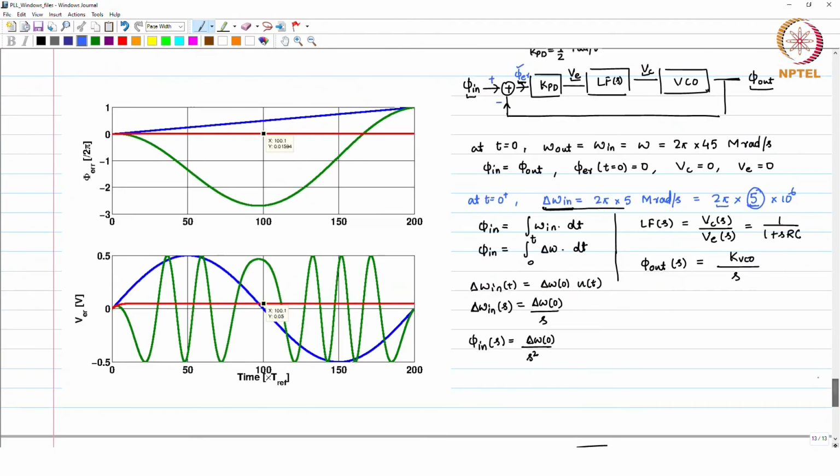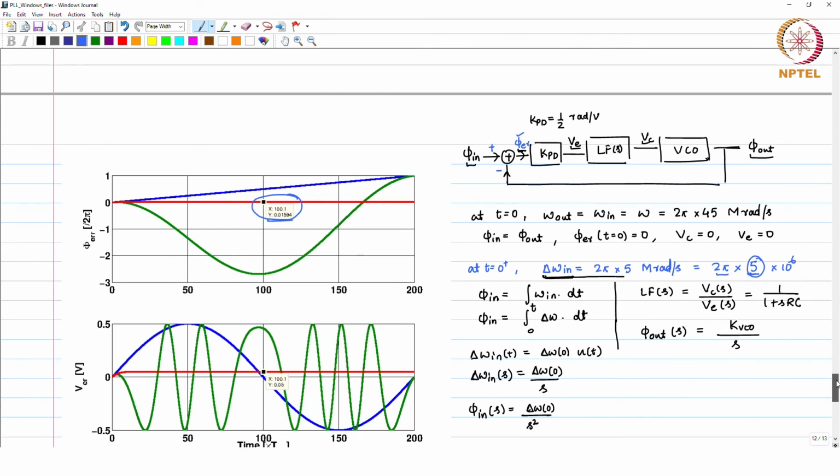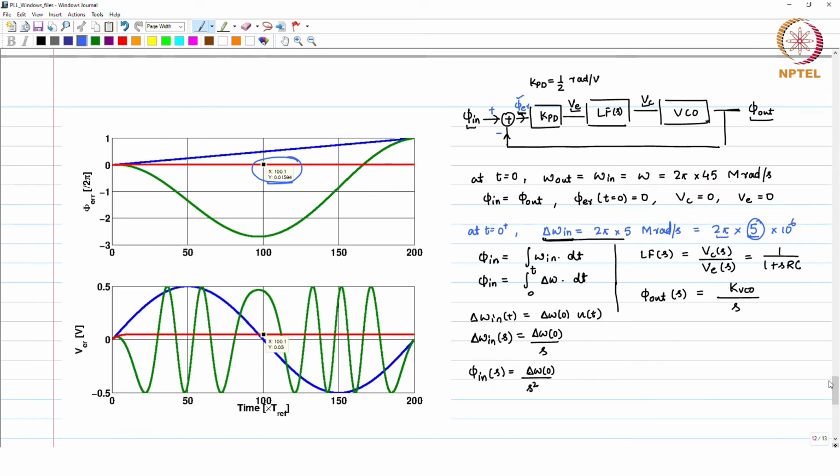Now, we did all this maths, and now if I say that this is the value after doing a small signal analysis, I go and simulate my PLL in the same way as we did in the previous session. You see that the phase error by 2 pi is 0.01594. This is the thing which I would like to emphasize, that in the previous example, when we had the frequency error to begin with, we went through time domain analysis and we figured out what the actual error voltage, control voltage and so on will be, and you understood the different plots which we had.